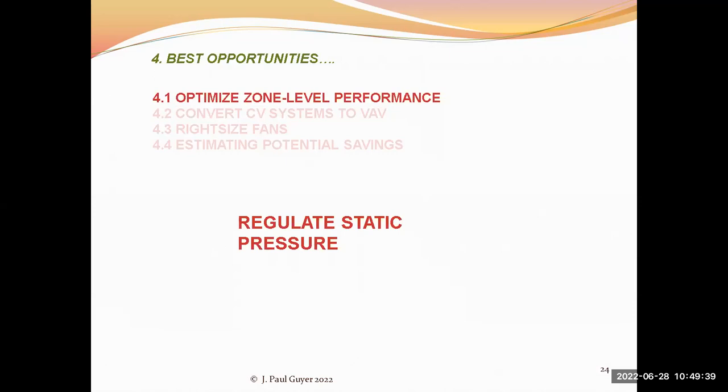So if the static pressure that the fan is producing is too high, you may be able to lower that static pressure and thereby conserve some energy.